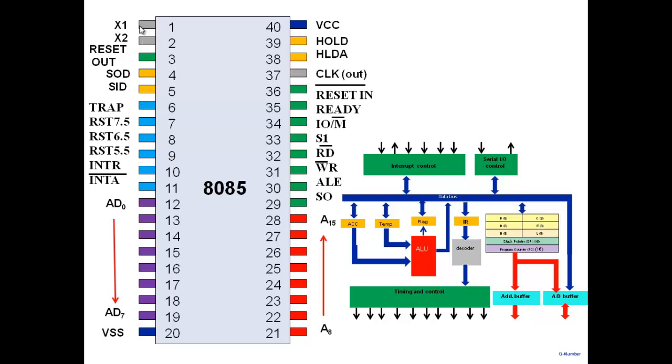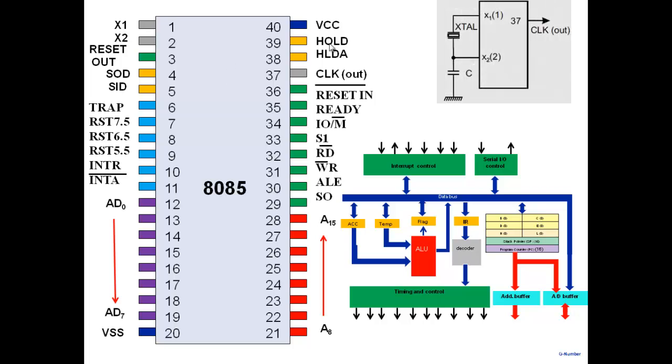And these are the pins for connecting, the whole thing is a clock system. And many of these microprocessors, the clock that you see here, so these are pins X1 and X2. And the clock is generated through a piezoelectric quartz crystal. It's in these early microprocessors, even now.